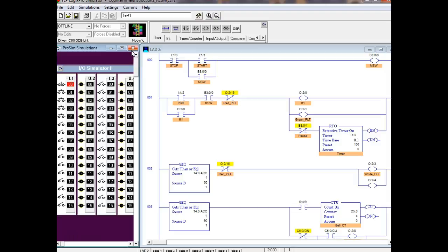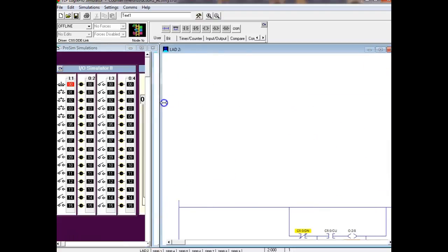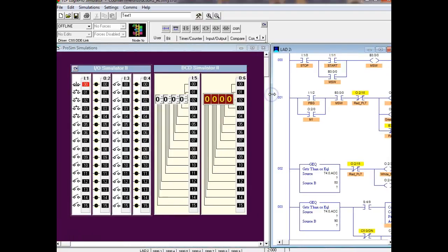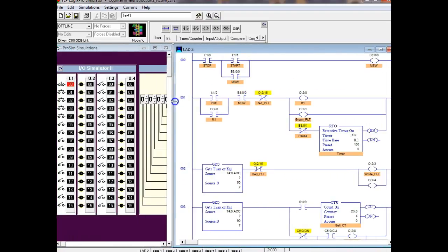We could start on rung 0 and just put in parallel off rung 0 all the way down, right? I mean, you could. The rung would get very long and start doing these arrows all over the place, where if you get past what it can display, it starts jumping into arrows. You'll see those things.